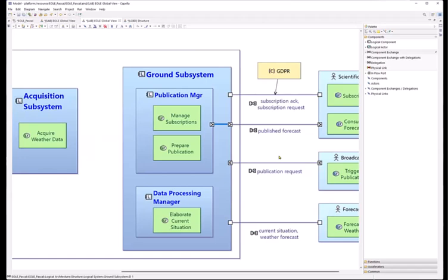And the very important thing is that when you create a component exchange, Capella automatically creates an output port and an input port in the direction of your movement. When you create a delegation, if it is an output port on the parent component, it's mandatorily also an output port on the contained component. Capella knows it. Because it's a delegation, ports have the same direction, whereas on a component exchange, ports have opposite directions.